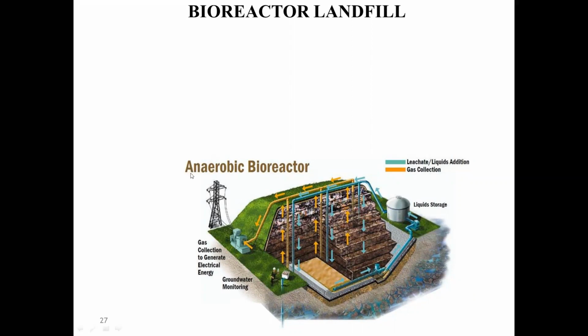In an anaerobic bioreactor, it doesn't require any gases, there is no oxygen required, right? An anaerobic bioreactor is one where you are not going to be requiring any oxygen for the disposal process, right? So in anaerobic you don't need any oxygen, hence you can cover this one. You can have aerobic bioreactors also. We supply the gases, wherein the proper application of the gases leads to the fastening of the process of decomposition, right?